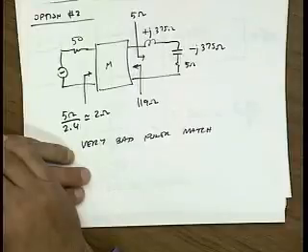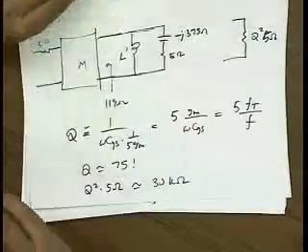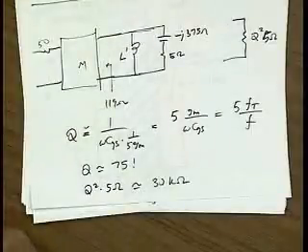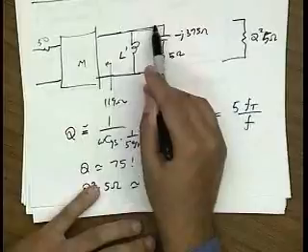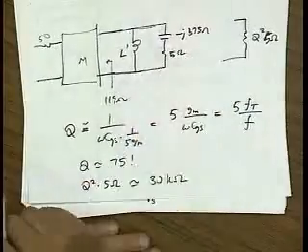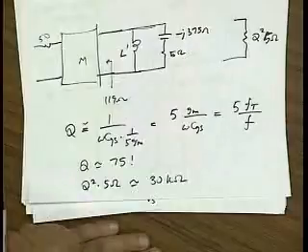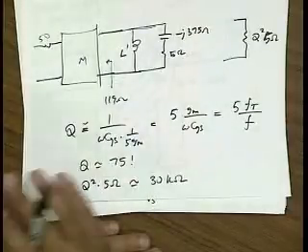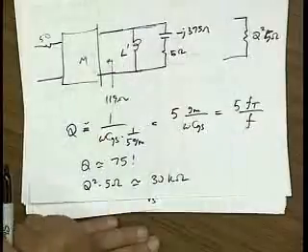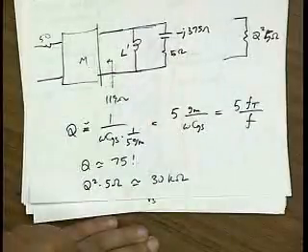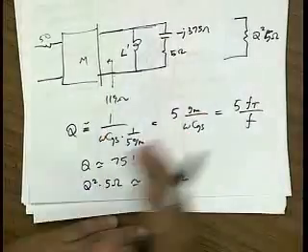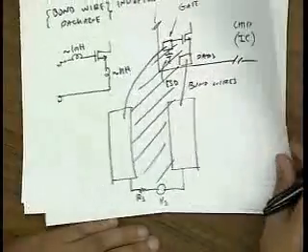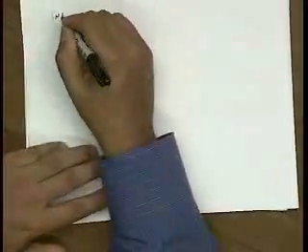I think the problem in option 3 would be the capacitor is so big that you want a high Q for the compensation. Then put a small inductor in series with those to reduce the capacitance. Then use option number 2, where I put the inductor in parallel with it. Yeah, so you mean I could put a little inductor in series here, reduce the Q of this network. You can play games, right? And I'm sure, in fact, you're absolutely right. You can make this work. It's not going to be simple, but it's going to involve a couple of stages, effectively, of matching. But at the end of the day, this is not what you have anyway. When you package it, you get these extra inductors. So the most popular way to do it is to use inductive degeneration.